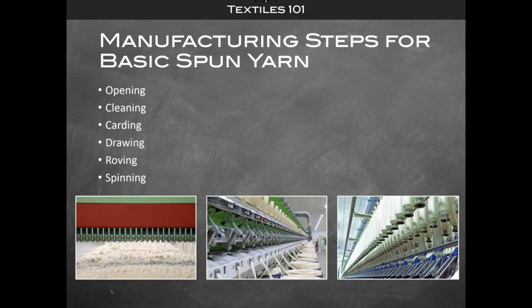These are the basic steps for making a spun yarn. So the first step is opening. You get a bale of fiber and you open it. Basically it's bound together in some way, and you open it, and after it's opened, the next step is cleaning. Cleaning would really apply more to a natural fiber like cotton or wool, which would need cleaning.